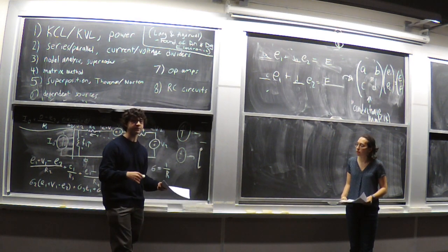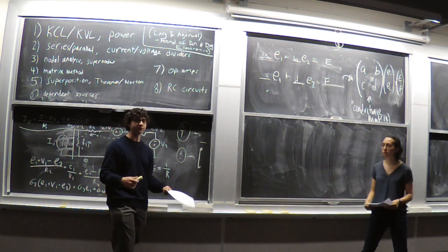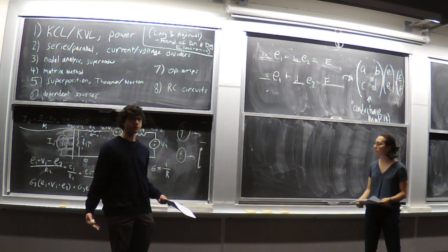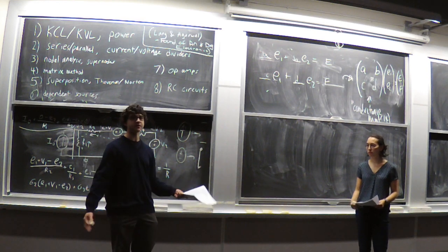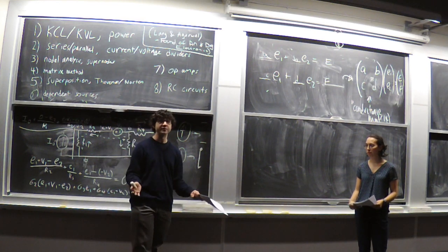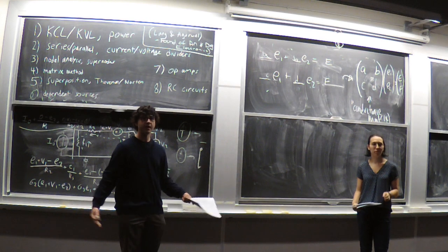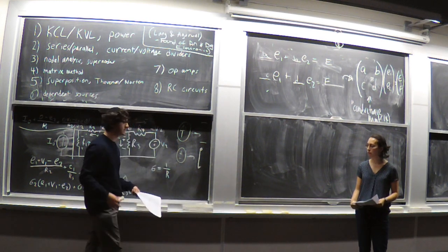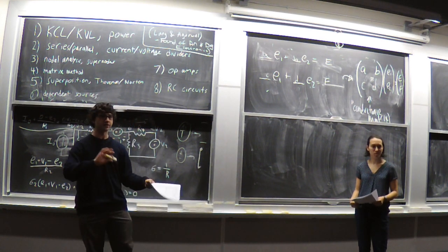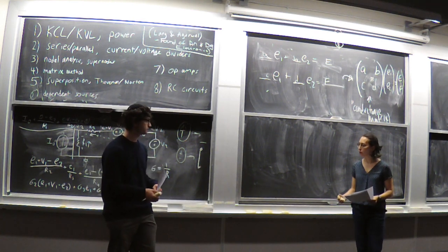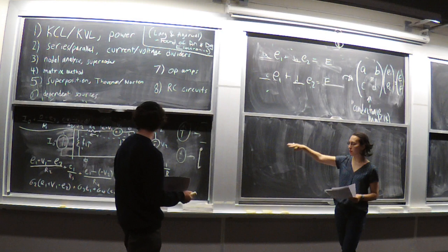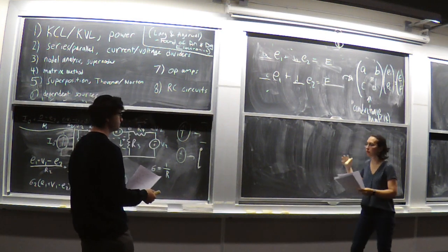Alternatively, a current source being set to 0 means that it is enforcing that no current will flow through it. Well, what circuit device doesn't flow current through it? An open circuit, just like air. And so that's why they simplified this, and that's good intuition to keep track of in case you forget which turns into what. Okay, and we'll go through the analysis of this after we cover superposition more formally.